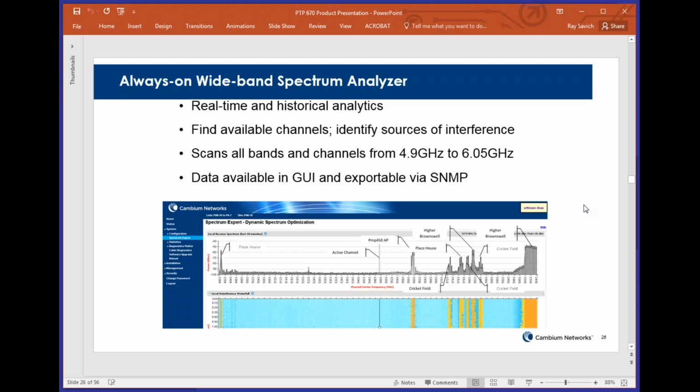So with respect to this, you move your channel to another band. In this case, there's a cricket match going on, so there's a lot of backhaul traffic being pushed back. Maybe that's the reason you're suddenly seeing a lot of interference for the duration of the game. In that case, you can shift within the 5.8 band to another separate channel to use.